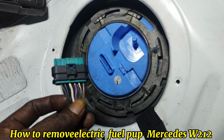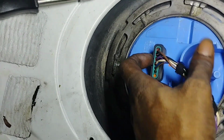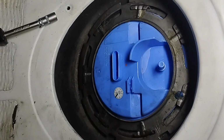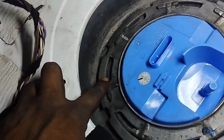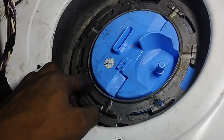How to remove electric fuel pump Mercedes W212. Now I will open the fuel pump. First remove wire socket to change the fuel pump. To open the fuel pump, the lock bracket on top of the fuel pump must be opened. To open the lock bracket on top of the fuel pump, open the lock by turning it to the left.